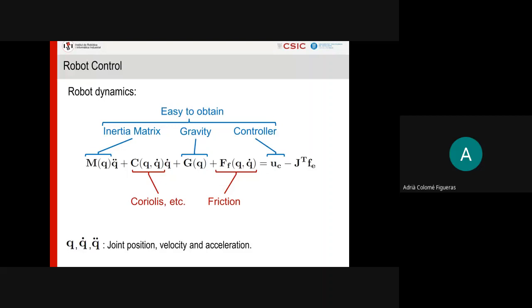And so a lot of problems come from friction, and it is one of the main factors that limits the capabilities of a robot for being compliant in its behavior. We also have, for instance, an acceleration that can be very noisy.